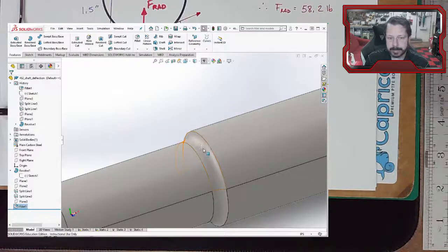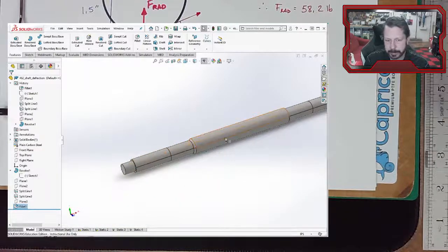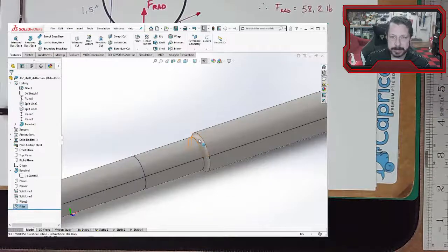And so now either I have to have smaller elements everywhere, which may or may not be a good thing, or I have to have an adaptive mesh where it's smaller here and gets larger over here. So it actually creates a little bit extra complications when you create the fillets and the ring grooves and the keyways and all that kind of stuff. I'm going to delete that.